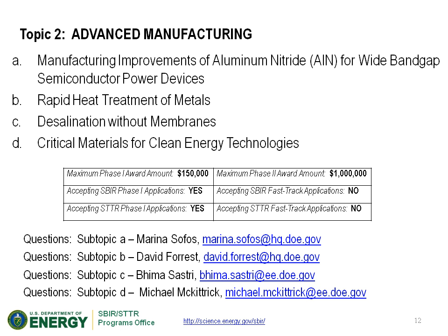By having this rapid heat treatment, you can, in some sense, defeat the physics of diffusion. You just don't have enough time for the atoms to move around to their equilibrium positions, and what you get is a heterogeneous microstructure that can give you novel properties.